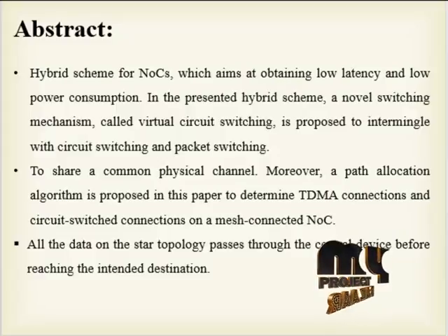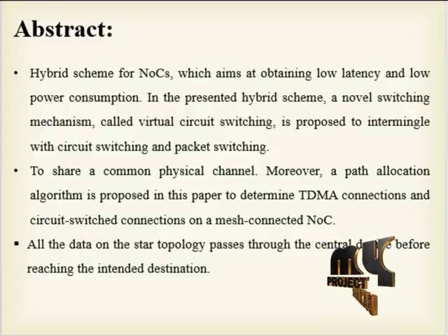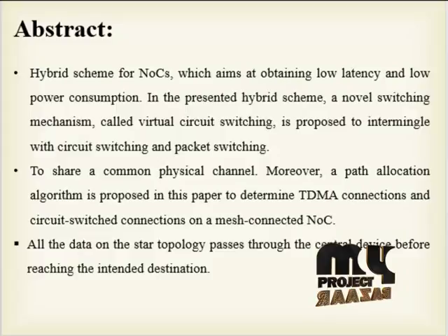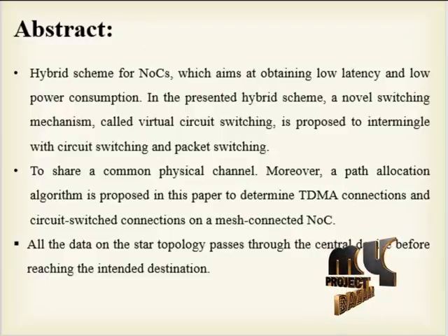The second technique is an extended carrier sense multiple access with collision detection for vertical broadcast buses. We introduce packet collision detection on the buses to statistically reduce the waiting time for packet retransmissions caused by collisions. Network simulation results are provided for the TDMA bus based 3D NoC, where inductive coupling and semiconductor technologies allow integrating various chips vertically in a single package.